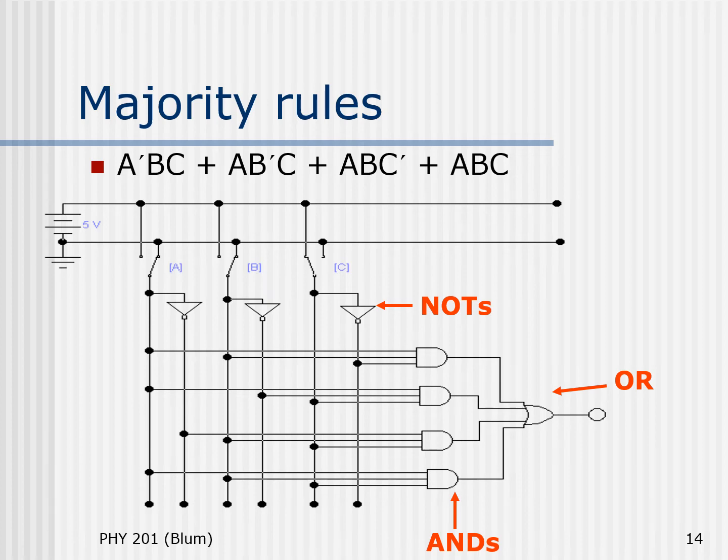Okay, now let's look at the AND gates, going vertically. The first AND gate is connected to A, B, and not C. The second is connected to A, not B, and C. The third is connected to not A, B, and C. And the fourth one at the bottom is connected to A, B, and C.